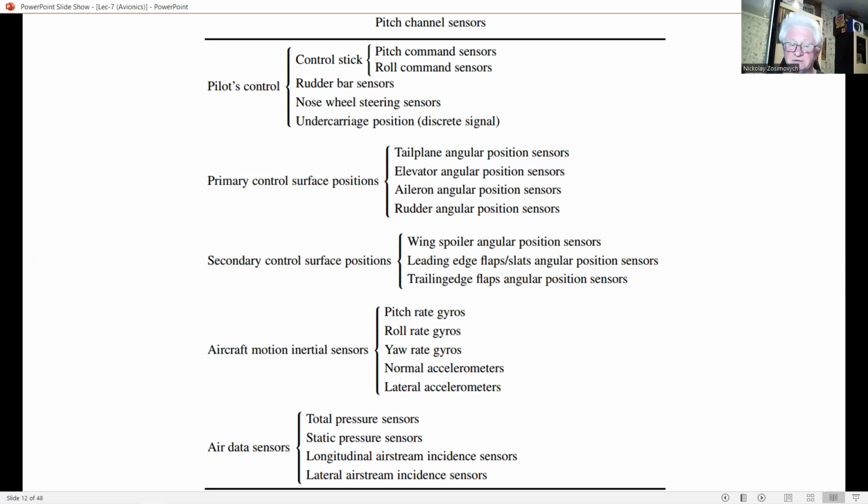Sensor failure detection: detection of a failed sensor by cross comparison of sensor data and majority voting. Sensor failure isolation and system reconfiguration: isolation of a failed sensor and system reconfiguration to survive the failure and also to minimize the resulting transient. Sensor consolidation: consolidation of the data from a group of sensors to use a single representative value for subsequent computation of the control law.